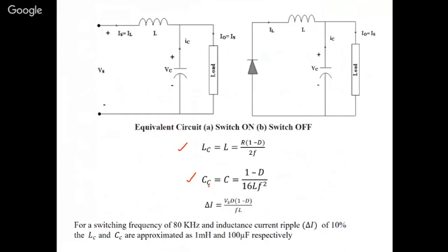Any standard book, Ned Mohan's also, or Rashid's, has given the L and C values for a buck converter, boost converter, or buck-boost converter. So substitute the values according to your requirements, get the L and C values, and you can design your own buck-boost converters.